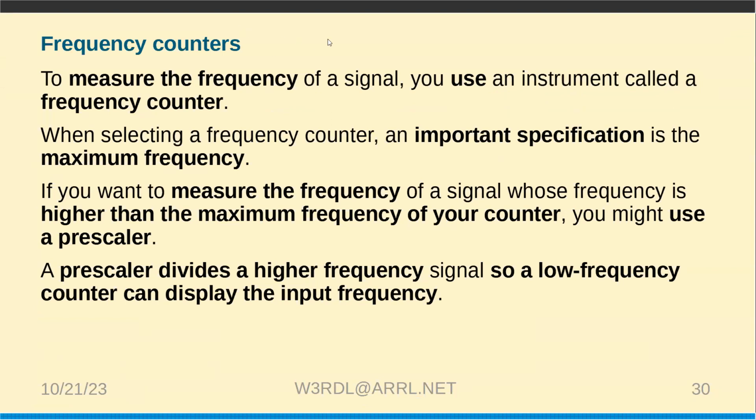Okay. Frequency counters. There's one thing. When you're measuring an antenna with an analyzer, the closer you get to your antenna, the better off you are, instead of a long feed line. That way you get the true resonance of the antenna, and a better SWR because of loss in the line. SWR at the antenna is worse than it looks. When you have a long feed line, it minimizes the effect of the antenna. If it's long enough, you don't need an antenna. You're just going to use a small patch cable.